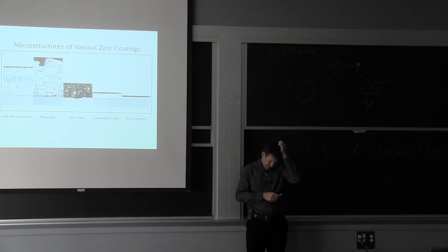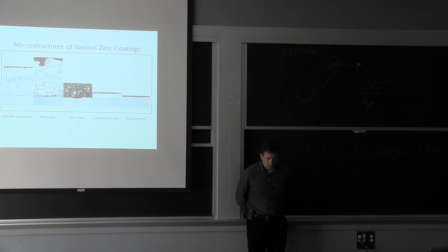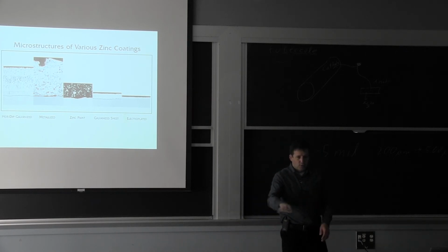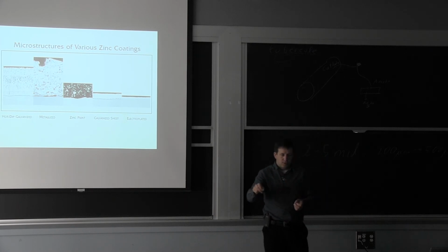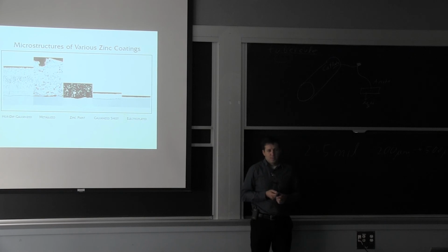There's a shop here on the North Shore, Dulcan, and they do a lot of galvanizing for large structures, anything from bridge tunnels to large building structures. What they end up doing is, after galvanizing, they will grind the whole surface. And what that does, the main thing is create these ridges for mechanical interlocking, but it's also deforming the zinc layer to try to get as much gas out of it very quickly. And they will guarantee their coating systems for 30 years. And the main reason they can do it is